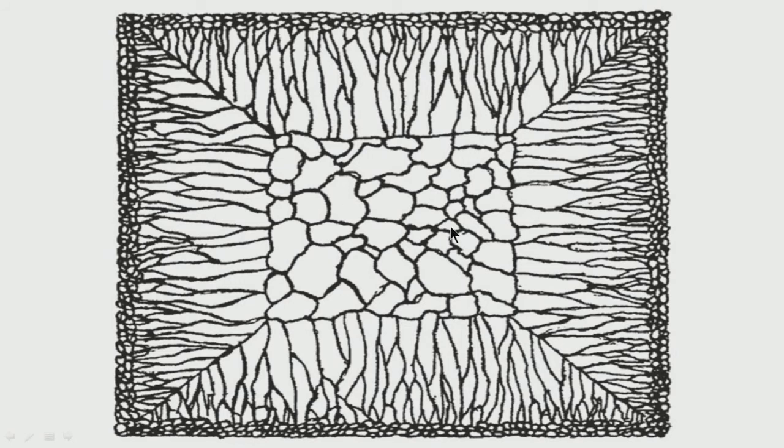That means, if you have high superheat, say 40 or 50 degrees centigrade, you may have columnar zone extending to the center of the casting. That means, you have columnar zone starting from the beginning of the casting to the end of casting. We have hardly any equiax zone if you have relatively high superheat. But if you can cast in a low superheat zone of say 10 or 20 degrees centigrade, your equiax zone will be slightly more, maybe from 20 to maybe 40, 50%. But for that you must have very low superheat.